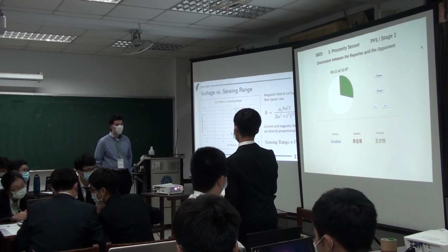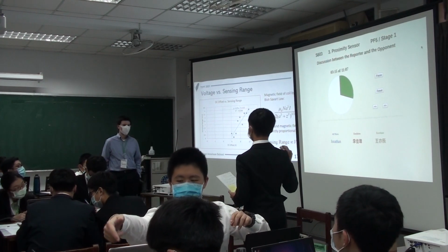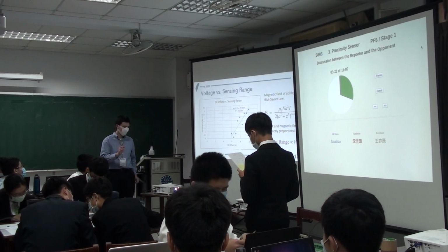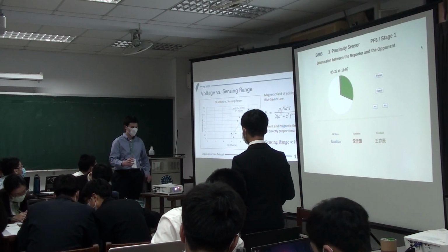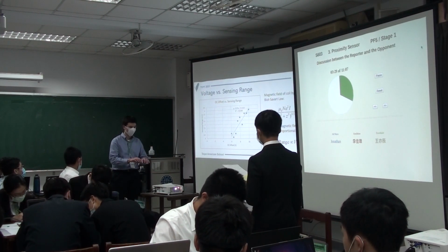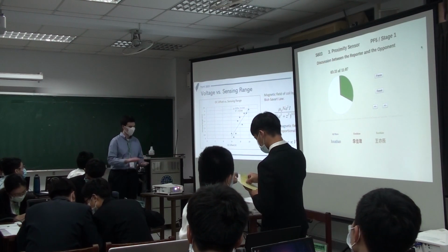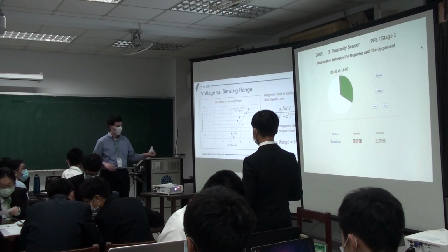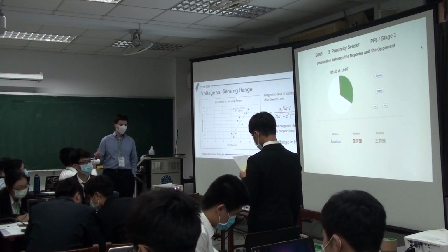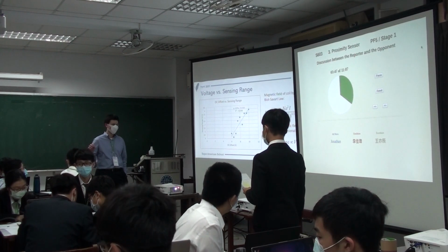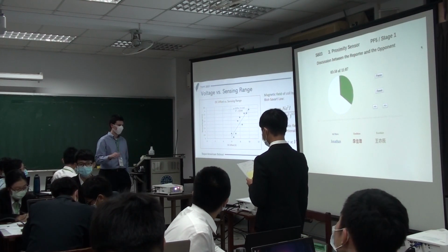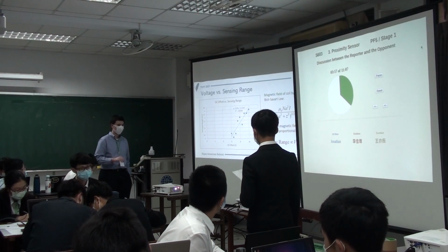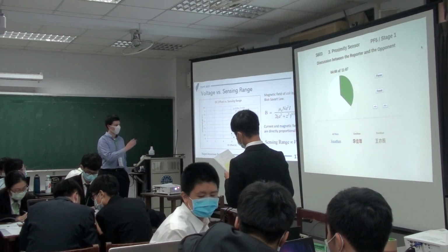Well, do you think the velocity will affect the experiment data you just showed, and how did it affect it? Okay, so that is a very valid point. I should clarify that all of this data is collected when the ferromagnetic object is still. We are not considering the ferromagnetic object's motion with our equations or with this data. However, we did run a couple of observational trials where, as shown in the video, we moved it. In the case of the motion of the ferromagnetic rod, due to Lenz's law, it could induce a magnetic field that's opposite the magnetic field of the actual conductor. But in our trials, we observed that this opposite magnetic field is very, very small, and that the most predominant phenomenon was still the magnetization.